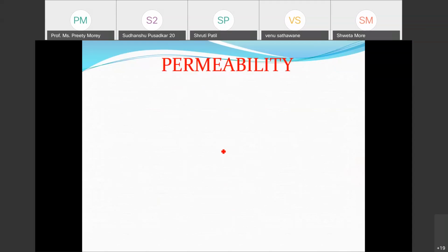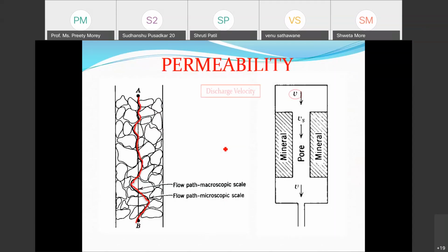You have to find out the permeability of even a reservoir, because if the water is flowing into the body of the reservoir from the ground surface, that will also not serve the purpose. Hence, permeability becomes a very important property of a soil. What I am trying to say is that the soil contains grains and there are voids, so water will percolate through these voids. It is not a straight line journey from one end to the other. It will pass as you get the flow.